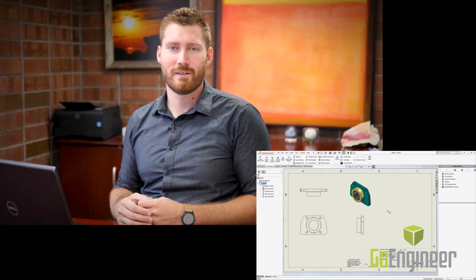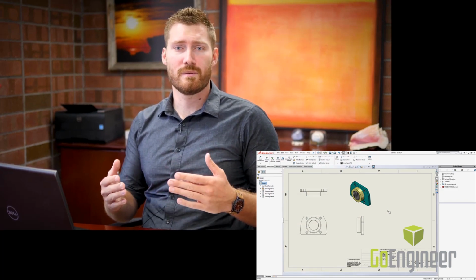Picking up from segment 1, this is segment 2, all about quick and easy ways to create annotations for your drawings. Now jumping back over to the model we created earlier, we're going to specify some virtual sharps. Now virtual sharp is if a corner came together and we've added a fillet.